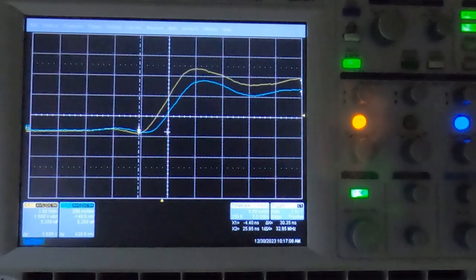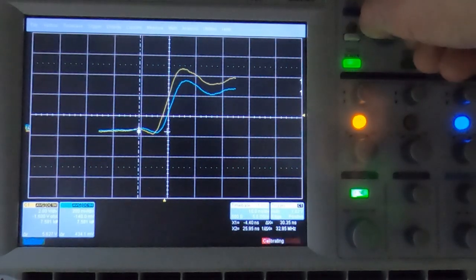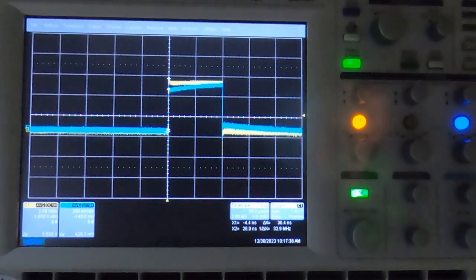And I have tested all the probes and they all give almost identical results, so this is not anomalous readings that we're seeing here. This is fairly typical for the probe types. So you can see that the more expensive probe definitely outperforms the lower cost ones, but at the speeds we're talking about, if we slow the scope down to something that's more in keeping with the type of signals that we are going to encounter, then you can see that you can't really detect the difference at all.